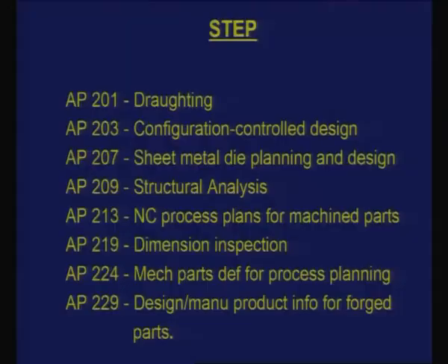And STEP is not a single thing; it has many application protocols which are called APs. So if I take STEP AP201, I can exchange drawings, two-dimensional drawings. If I have a STEP AP203 translator, that means I am able to exchange the geometry, part geometries, assembly information, etc. So you have a variety of cases which can be done.